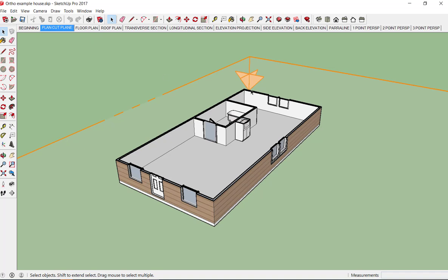It's almost like where this cut plane is cutting through the walls, you can see that the line is a little bit darker. If this was a big sheet of glass and I traced this on the sheet of glass, there'd be no distortion because it would be a one-to-one relationship. If I measured an inch on that sheet of glass, it would be an inch on the wall. That's the beauty of floor plans: since they're totally square and perpendicular to the world, there's no perspective foreshortening, so you can scale off of the plan. Everything's in its proper scale and relationship.